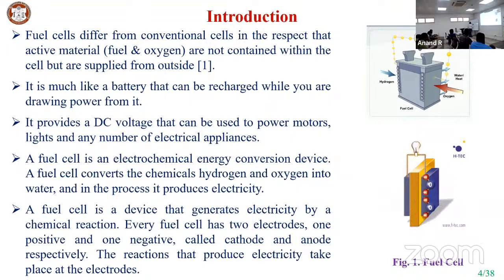Then the removal of water is also a big problem in the hydrogen fuel cell. Once the water is formed inside the cathode zone, you need to expel the water immediately, otherwise it is going to create a problem called water flooding.